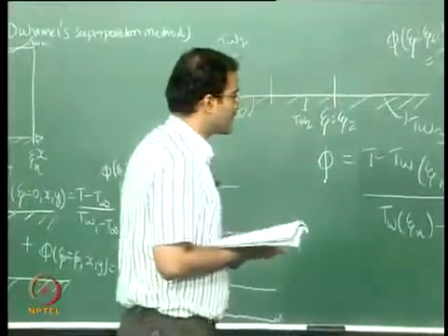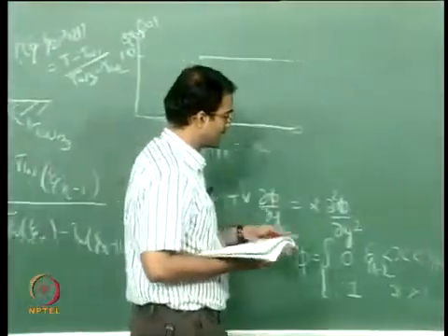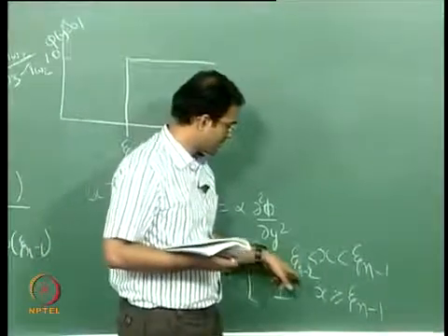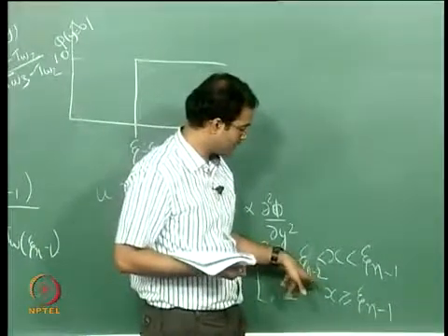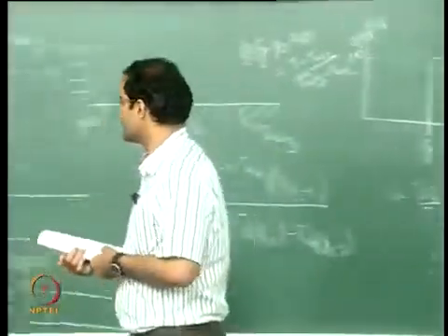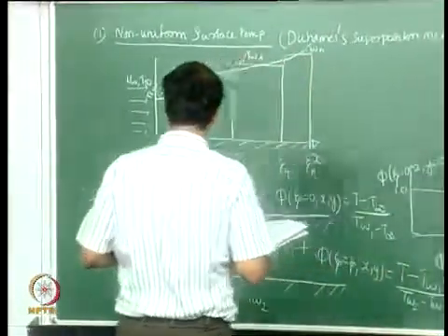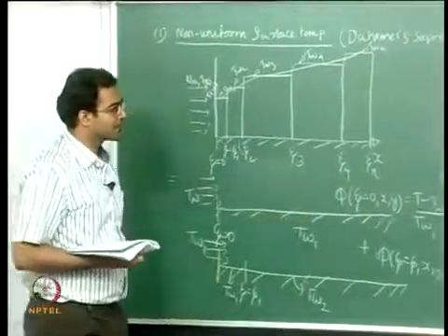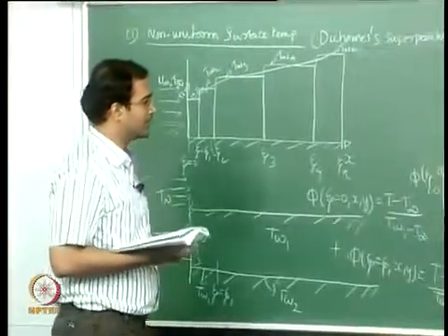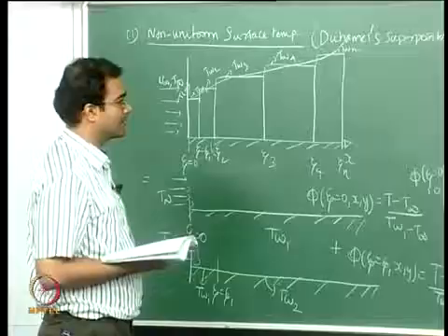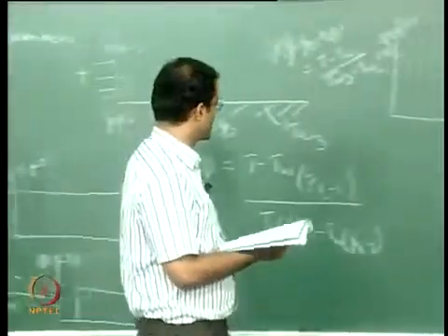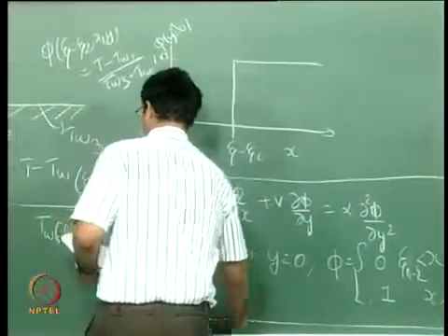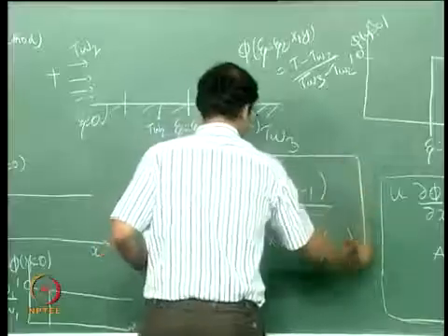When you start with of course something negative, it means it is free stream, so there it will be 0. Then when you start with n equal to 1, up to eta 0, basically you do not have any heat transfer. From here onwards, greater than that, you have your phi equal to 1. So this is your generic solution, and this is your generic way of non-dimensionalizing phi.